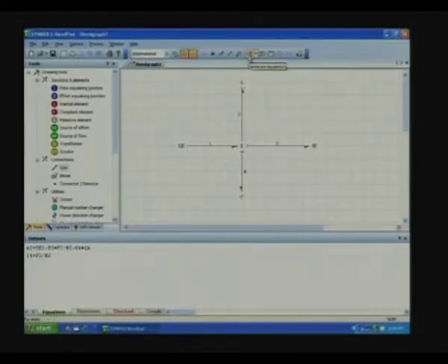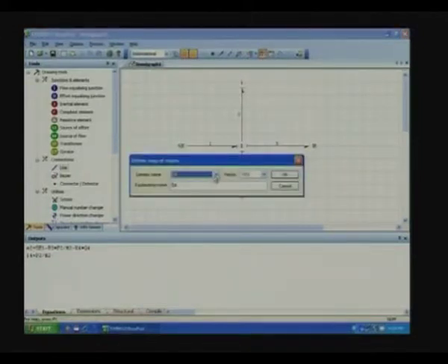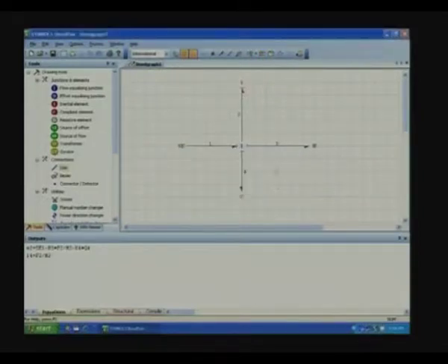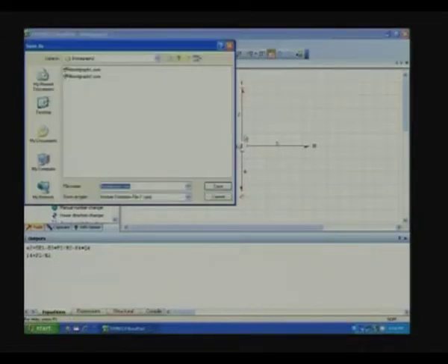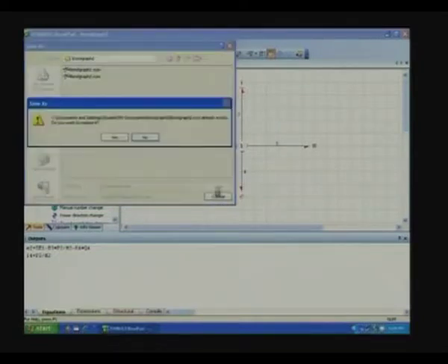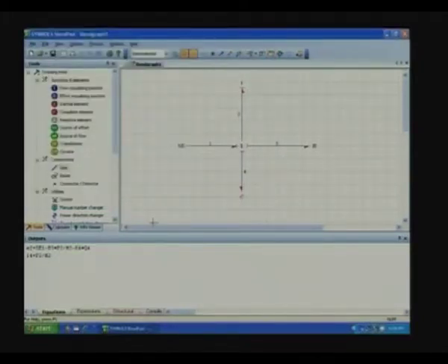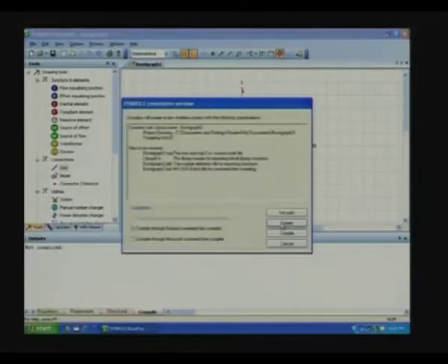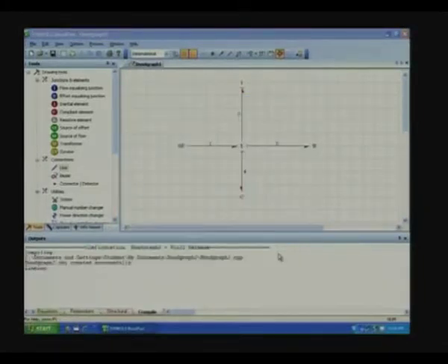Now, we have already generated the equations, now we have to define the maps. What are the state variables? Q4 and P2, we could give a name, but we understand what they are. So, let us leave that. Then it is to generate the simulation code. I will give it as bond graph 2, same name, it overrides, fine. Now, we have to compile, this is a compilation. So, set and compile, let us see what it writes.